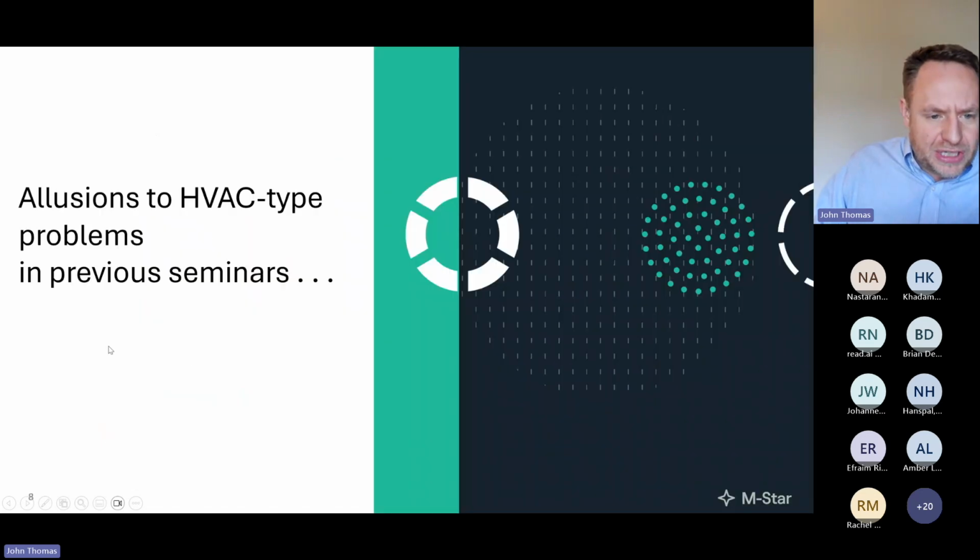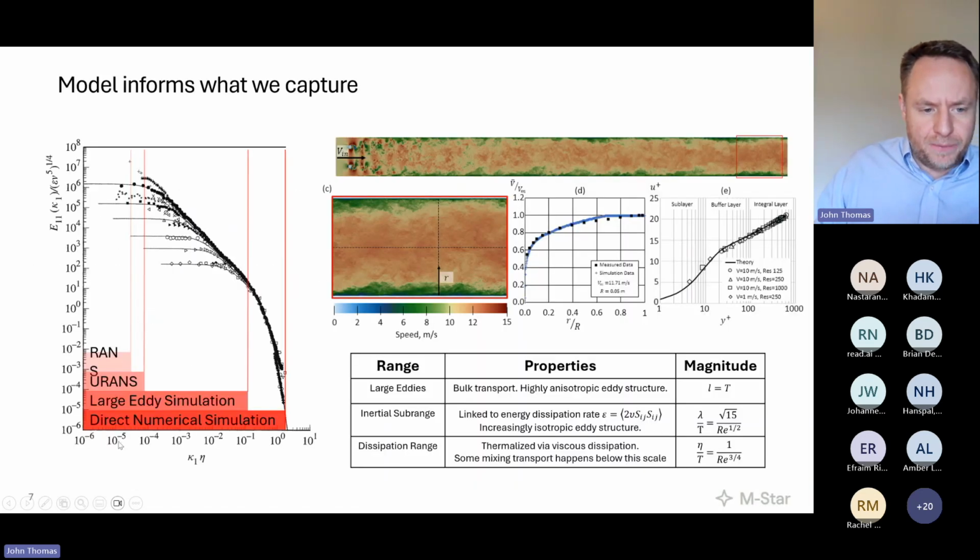And so when we look at this simulation resolution here, if we're doing direct numerical simulation and capturing all the way down to the Kolmogorov scale, that will be very expensive in high Reynolds number systems with large length scales. But we're not doing that. We're doing large eddy simulation, which means in as much as we get down to the Taylor scale, we're going to be capturing the relevant physics. Things below that will be isotropic, but that's where the LES filter works best.